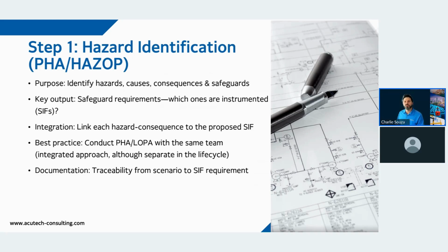So you need to not just get to LOPA and say we need RRF of 100 or we need SIL 1 on this interlock, but accompany and make sure that your functional safety team or your design team is keeping that all the way into installation and operations.